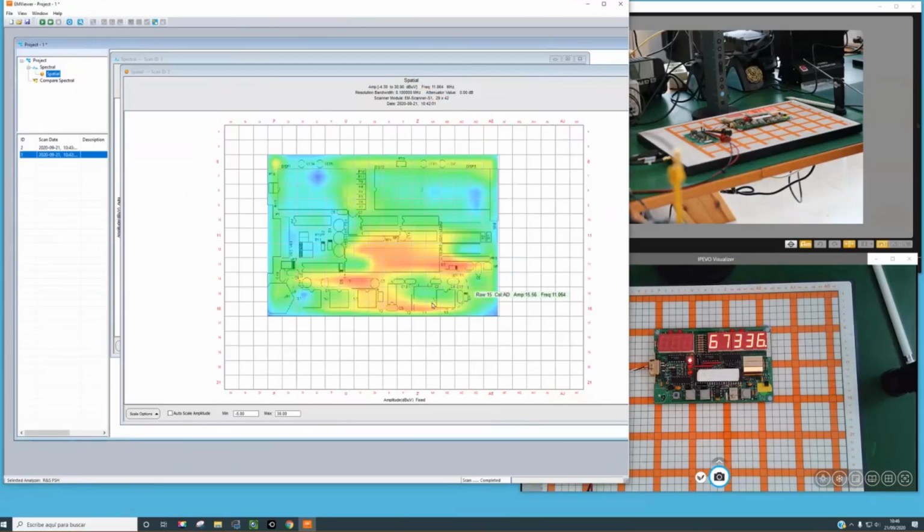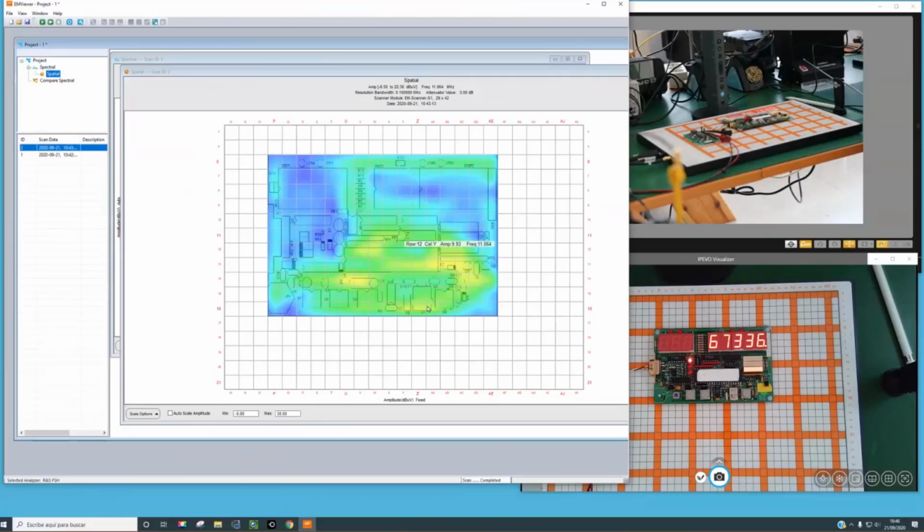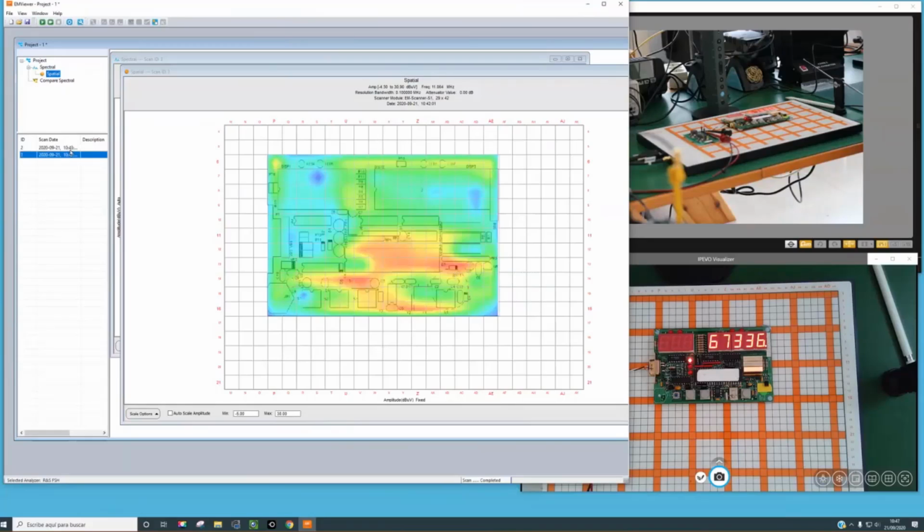I have introduced the decoupling capacitor. The decoupling capacitor for this microcontroller has a wrong position. It's very far from the microcontroller with a very big loop, but the difference between the availability of the capacitor or not is really well appreciated.